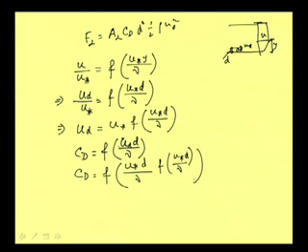So, again what we are finding finally is that CD, ultimately this is also a shear Reynolds number. So, it can be written as a different function, say f1 of U star d by nu. So, we can write CD as a function of U star d by nu.